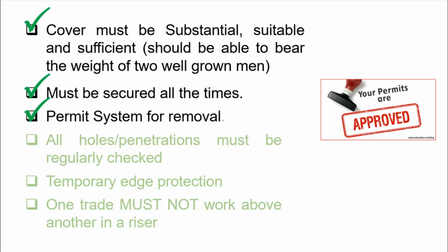Removal of the opening covers should be by permit system only, and all hole penetrations must be regularly checked. Remember that construction is not fixed, it changes every minute, every hour. So regular checks should be done to make sure that the covers are still intact, especially if there are workers working around the holes and penetrations.